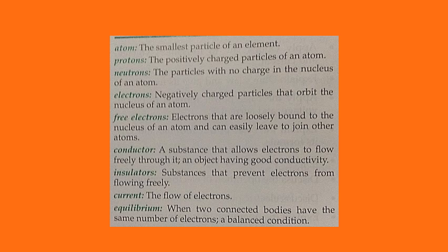Electron travel. A material in which electrons move easily is called a conductor. A material in which movement is difficult is called an insulator. Pure metals, carbon, and most liquids are excellent conductors. Among good insulators are dry gases, glass, rubber, mica, silk, and cork. According to the commonly held electron theory, metals conduct electricity well because they have a great number of free electrons. In insulators, there are few, if any, free electrons. Thus, little or no electricity is conducted.